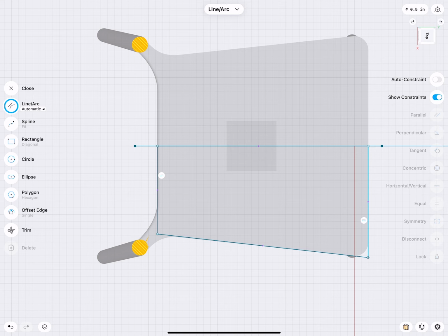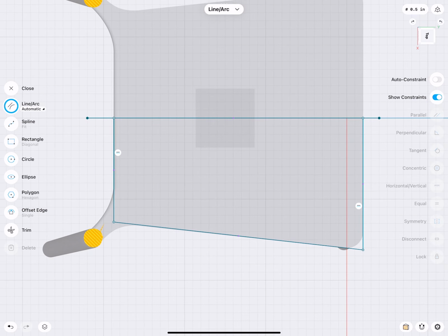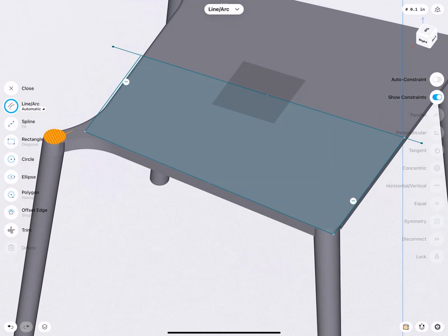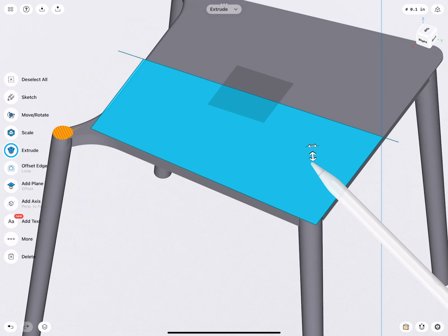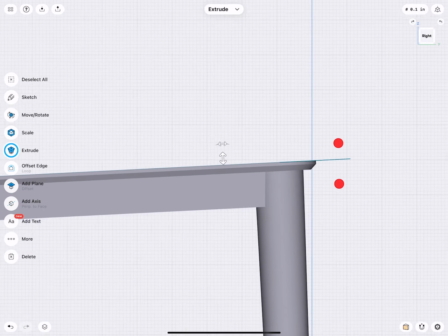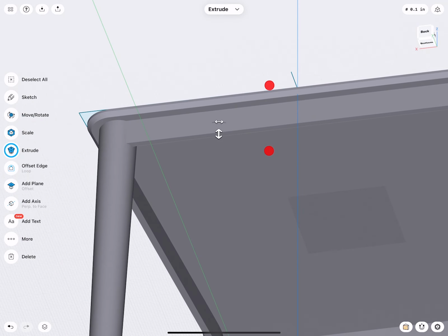In this exercise, because I really want to very quickly rebuild this design, I'm not going to be very specific with the dimensions. Sometimes it's actually also very good not to be too specific with dimensions in general, because it helps me to be more creative. Okay, the sketch actually is done. It's very basic. That's all I need. I have down here a rounded edge, but this I will rather do via a fillet. So I can select the surface and then decide, well, okay, how far do I want to extrude this down?